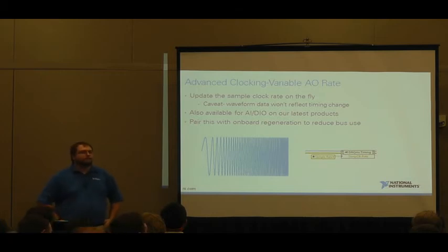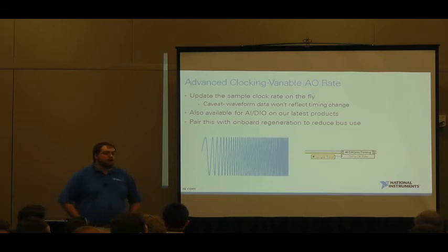Does this mean that if you've got it set for a really slow rate, you'll get at least one cycle of that rate before the switch? You will get one sample clock of that rate before you switch. A sample? It's not tied. Okay. The timing engine doesn't know what a period of your signal looks like. So it waits until the next full sample clock.